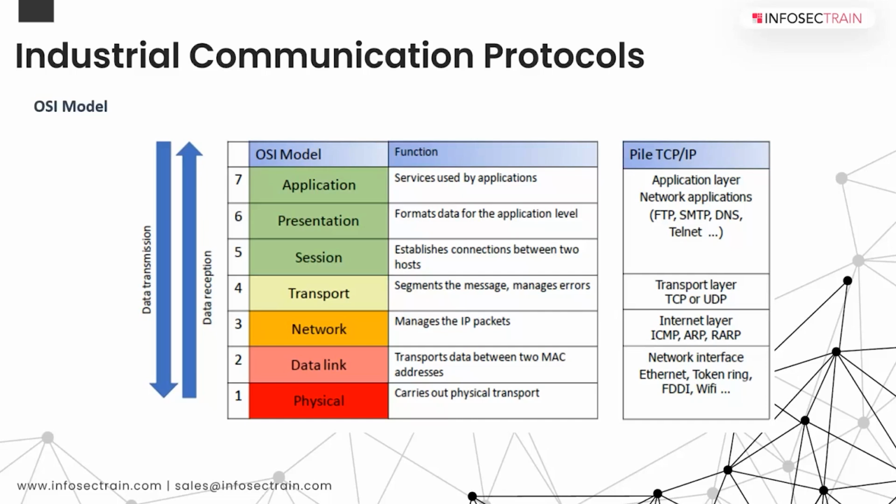Level 0 to level 1 is usually analog or a digital signal, depends. But there are smart devices like field bus configurations and so on, where they work on the field bus protocols. But if it's an analog, then level 0 to level 1 doesn't need any protocols. But usually from level 1 to level 2 and so on, these protocols are needed for various systems.